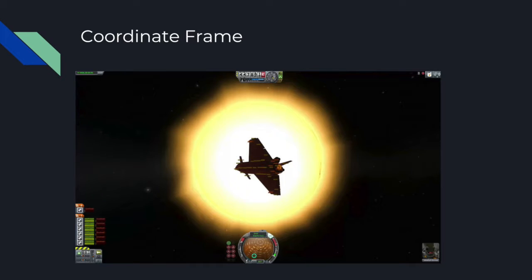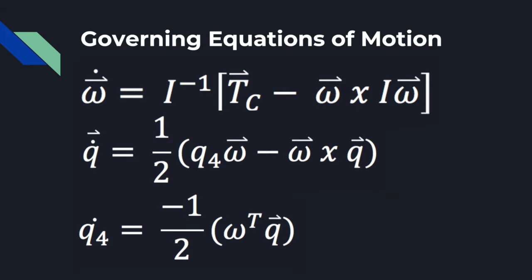This is a continuous process because the system has to continuously check its orientation to maintain max efficiency. The coordinate frame is a body frame with the following axes orientations: X is pointing toward the sun, Y is pointing in the positive azimuthal velocity direction, and Z follows the right-hand rule off of these two. The governing equations for this system are similar to the last homework assignment equations, these being angular velocity and the quaternion. However, in this example, the quaternion does matter as the orientation is what we are trying to control.